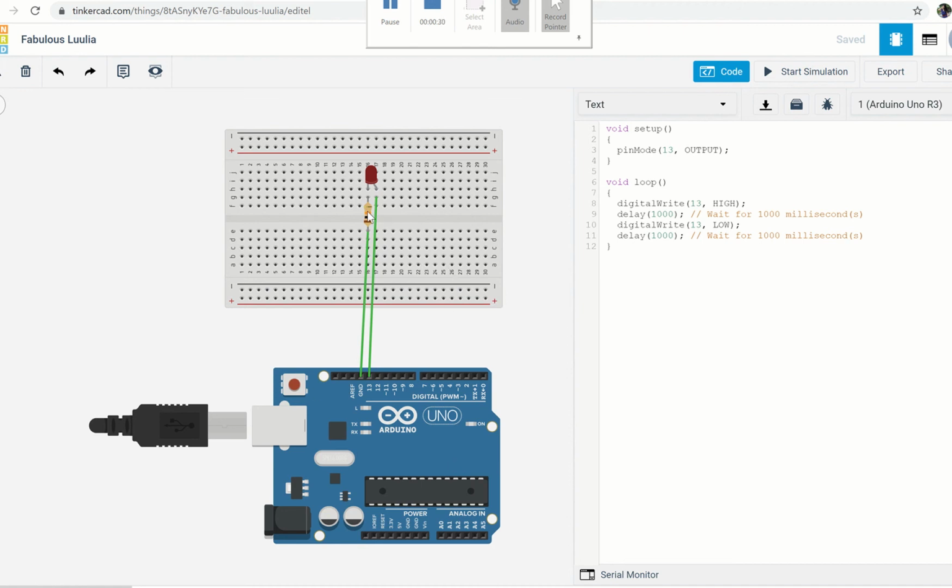And then we also have a resistor right here, and then there's also the LED and a couple of wires. The way that's going to be done is, basically 13 is going to be the output of the voltage, and make sure the anode, the positive side of the LED, is connected to the positive side of the power supply, which is digital pin 13. If you flip it, then the LED will not be on. And here's the resistor. Then come back to the ground.